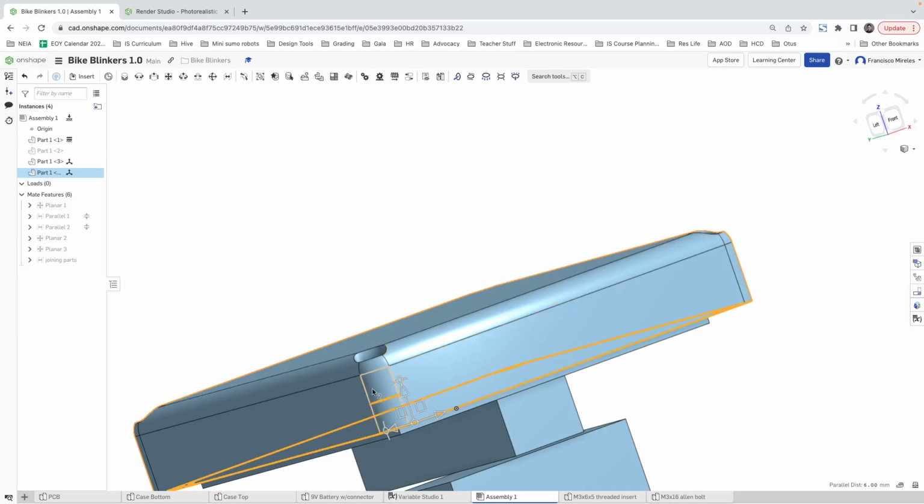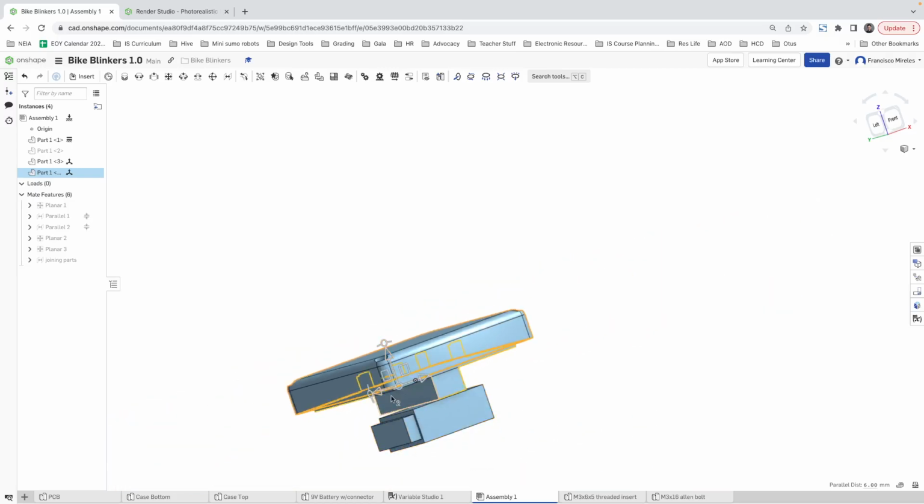So if I put a bolt here that is M3 by 16, 6 of those 16 millimeters are gonna be consumed here. The other 10 would be consumed in the other part. So I'm gonna do like a hole of 12, if that makes sense. Yep. So that's what I'm gonna do. A 12 millimeter deep hole.